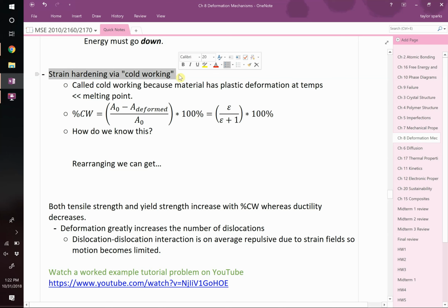And in principle, if you keep on, as a blacksmith, pounding on a piece of metal, it will eventually fracture, right? You keep on deforming it. It's going to keep on flattening, and then it will split in half. So there's a trade-off for blacksmiths on how often do you want to keep putting it back in the furnace versus the risk associated with it fracturing and breaking in half and then you starting over, right?